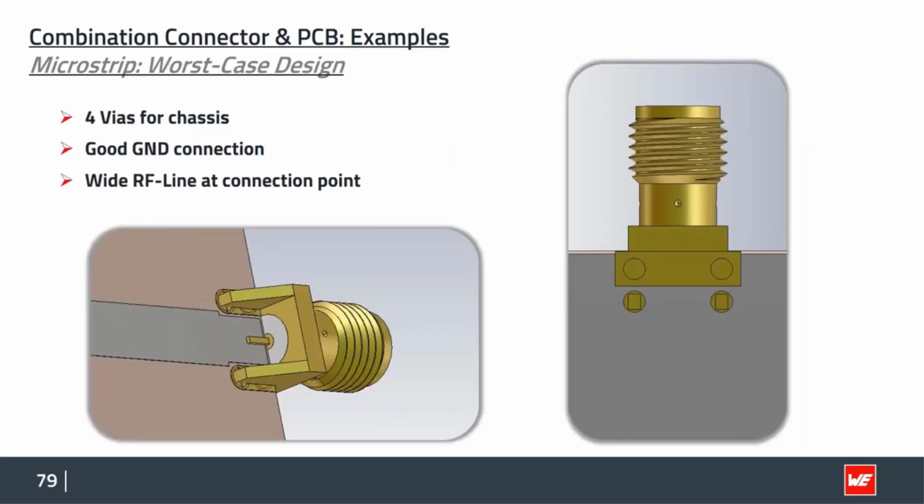The first thing, optimize the ground connection. What we are doing is, instead of this one via, we set a second one, like a little via fence here, because we said it's behaving like a coplanar waveguide here in the interface part, and make a good ground plane here that we really have the ground from the beginning rim of the PCB.